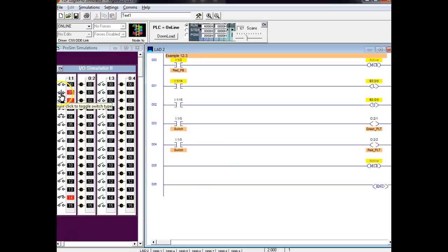So this is what we're talking about, latch. I'm using these guys down here. I'm going to change these to push buttons, by the way. So here's unlatch, here's 15, here's latch. Let's say I do an MCR right now. Here comes switch 2. The latch stays, and all the other outputs are what? Gone.